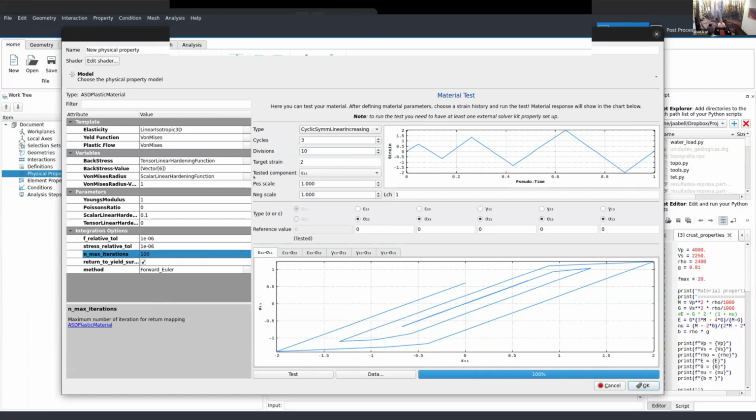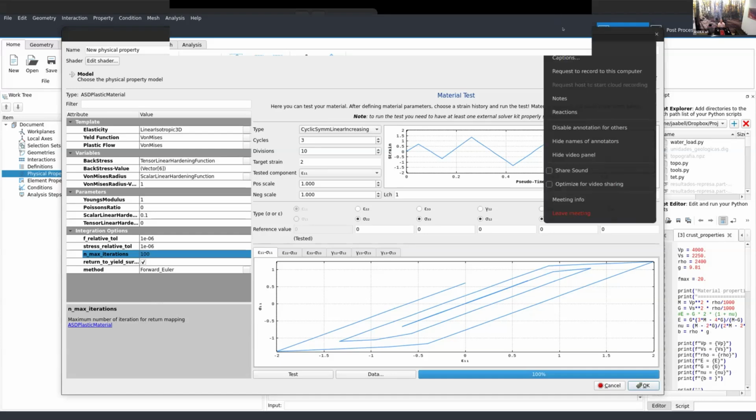And just to recall the question about the user, this one was a new material. When you have a new material in OpenSees, in your own version of OpenSees, now let's imagine the ASD material is not in the public repository, it's your own material that you developed. You have two options, actually. One is to use a built-in tool that we have there, which is under ND material. There is a custom ND material, where basically you can specify all the input variables as a string. So STKO will not do any type check on that. And that's the easy way.